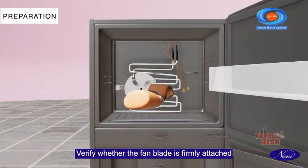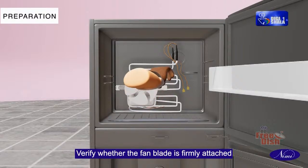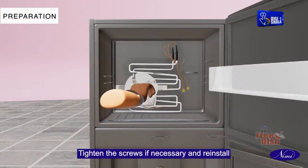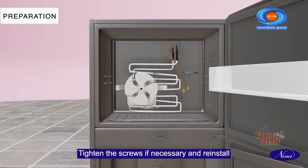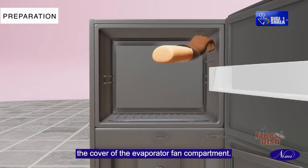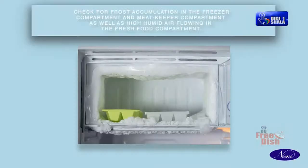Verify whether the fan blade is firmly attached with the blade set screws. Tighten the screws if necessary and reinstall the cover of the evaporator fan compartment.